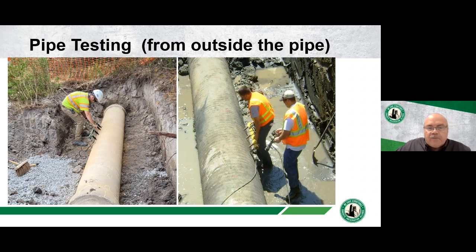We would mark out 1 foot increments on the pipe section that we're testing, and we try to collect data on the clock: the 12 o'clock position, the 11 o'clock, 10 and 9, 1, 2, and 3. Sometimes during excavation, we still want to have the bedding material supporting the pipe. So generally, we wouldn't get information past 3 or 9 o'clock, unless it's pretty complex, and then you have to support the pipe, and that can get a little tricky.